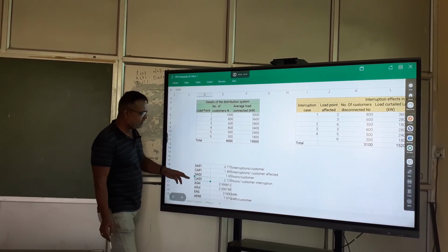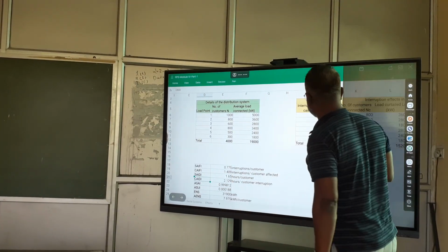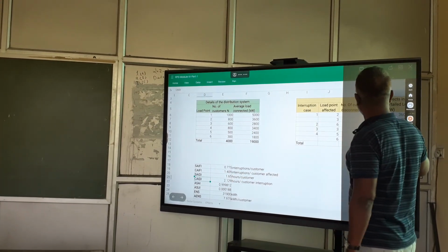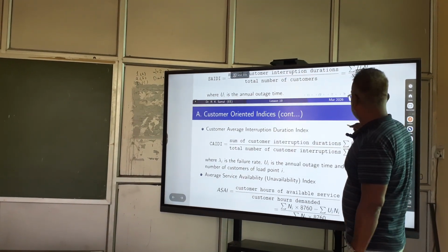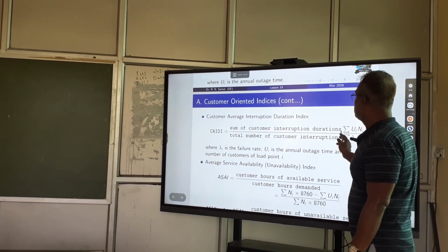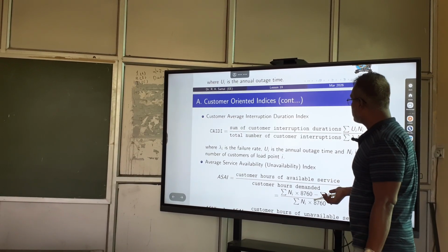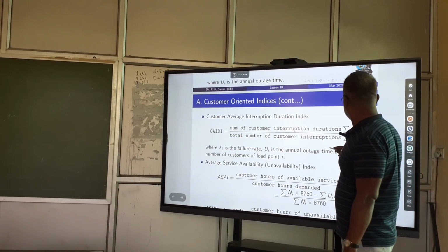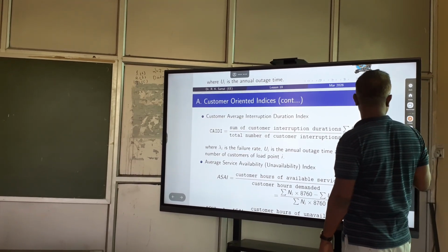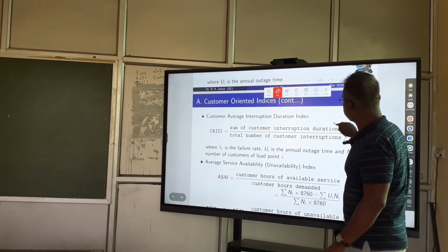Next, CAIDI, the customer average interruption duration index. What is the formula? Sum of customer interruption durations divided by total number of customer interruptions. What is this?